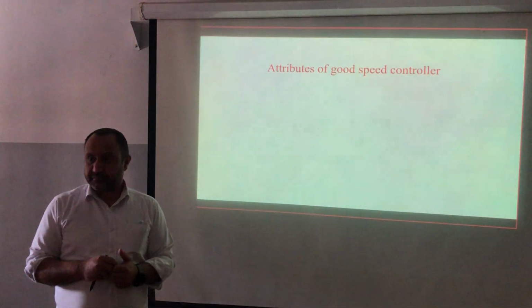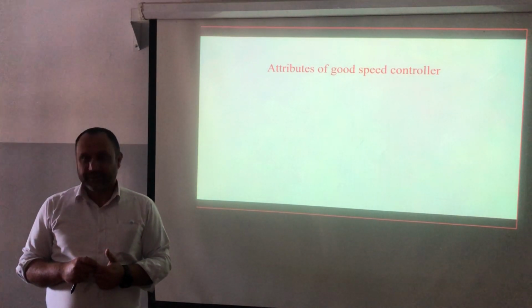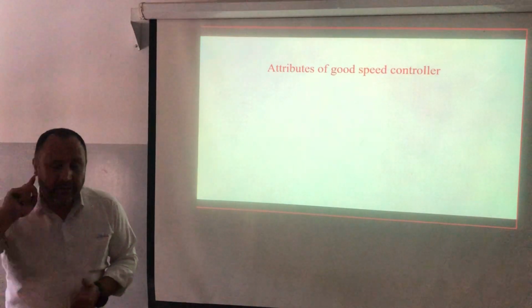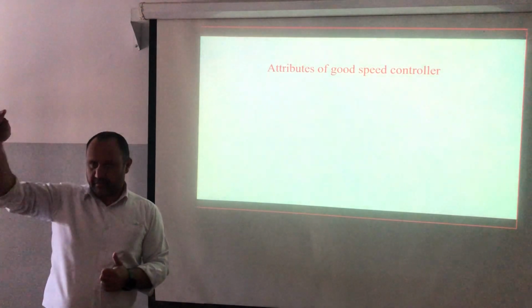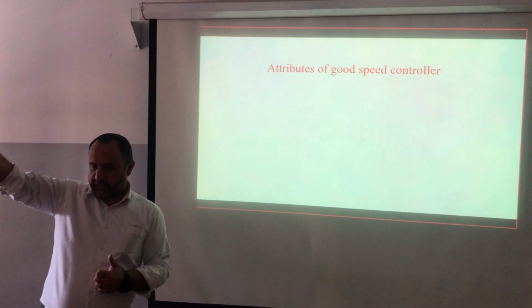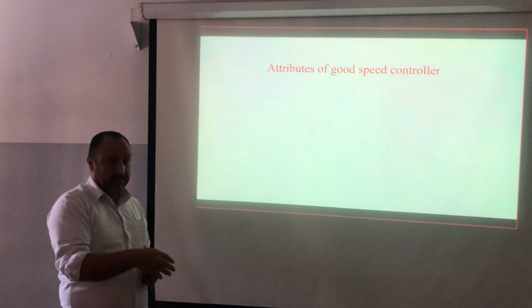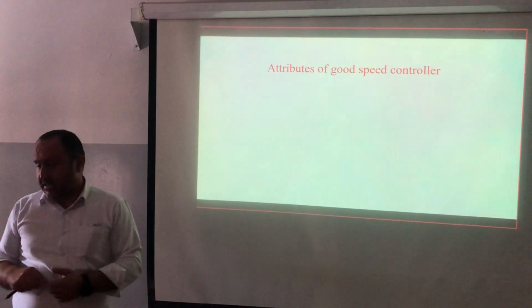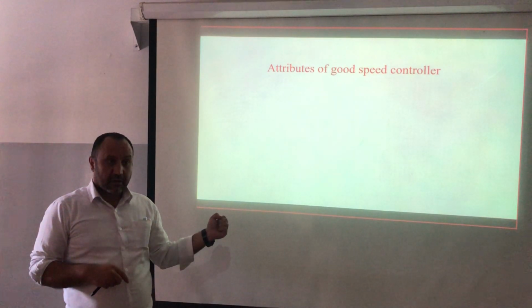What else? Speed up to a certain limit, which means that I don't need to over-accelerate or reach a speed over the maximum capability of the machine. And this is a design parameter from the mechanical engineer. In general, the shaft can handle a certain speed. Choose the control to give the best efficiency.